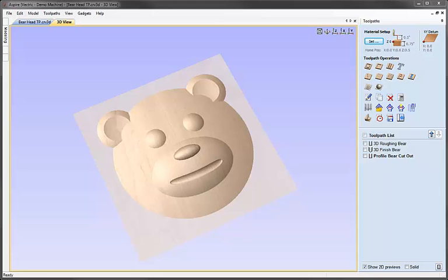Next we showed you how you can edit the 3D components that you've made, and we adjusted the Z height of our part. Once we had it at the final size where we were ready for machining, then the last job before we calculated the toolpaths was to create a vector boundary we could use in order to govern the area that those toolpaths would be cut in. Once we'd done that with the help of the layers, we went over to the Toolpaths tab and we set up our material in order to relate our part from within the software to how it was going to be set up on the machine itself.